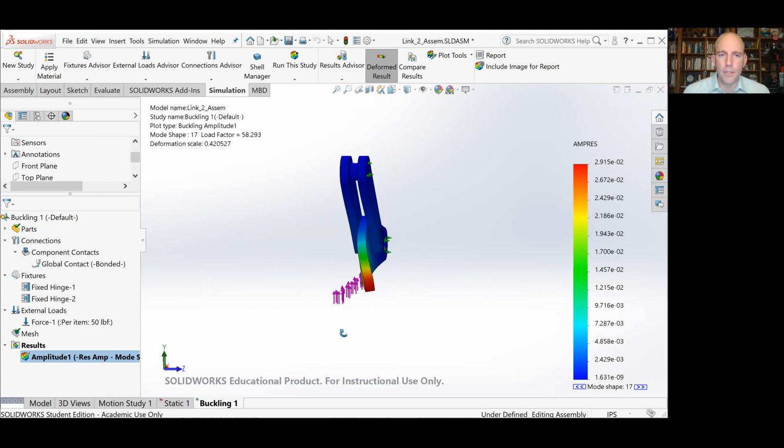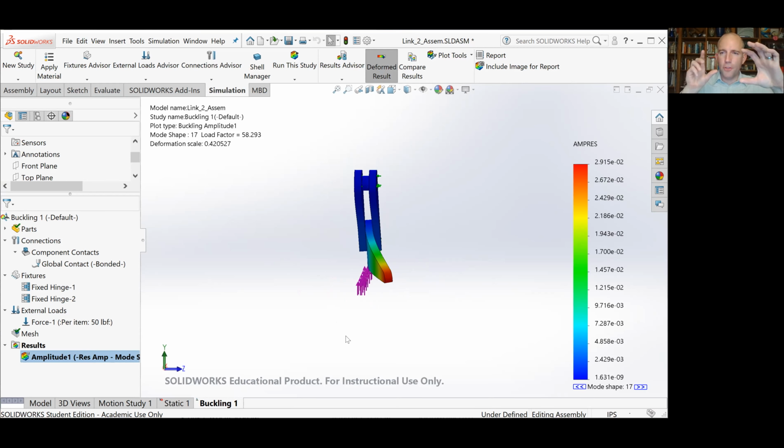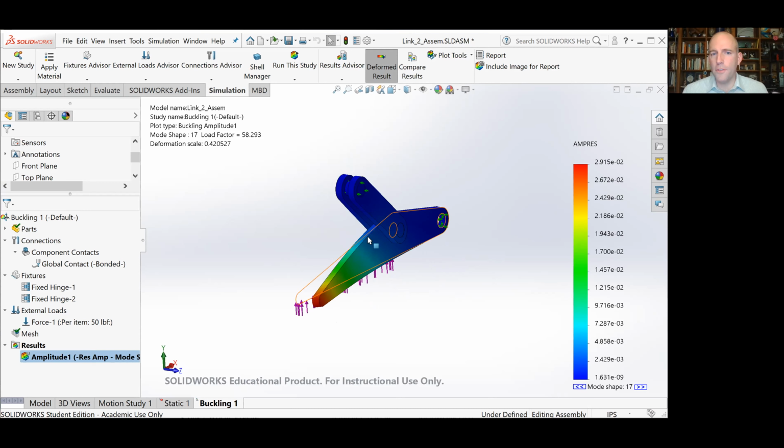But it doesn't always look like those shapes in the plane that we draw, because you can imagine it's a little easier for this thing to pop out if it bends a little as well, because the cross section is thinner than it is tall. So it's much wobblier and more flexible in that out of plane direction. And so we have compression, we have something that's skinnier than it is tall, and those two things lead to this out of plane buckling shape.